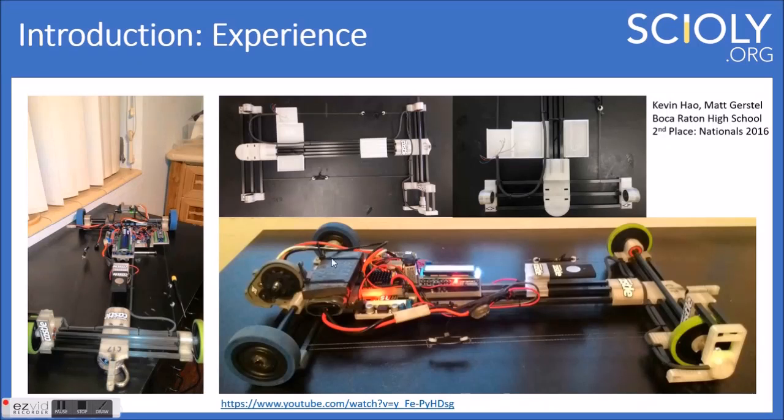The steel brick here, we wanted some more weight over the rear axle just because we were accelerating so much, and we just needed more frictional force, so we increased the normal force. In retrospect, it might have been better to get new wheels. We used these blue wheels, but they were not as soft as, say, the orange or the green ones, and I'll go into that a bit more later.